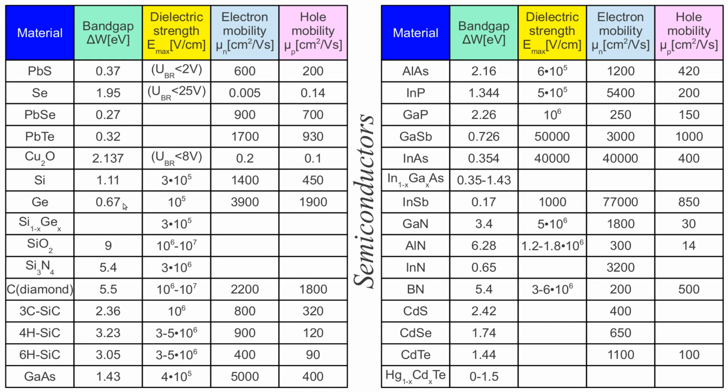Semiconductors mainly have band gaps within half a volt at room temperature, and perhaps up to 3 volts for gallium nitride semiconductors that have some useful performance at room temperature. At cryogenic temperatures, other compounds may be useful that have a much lower band gap, useful to detect infrared radiation.